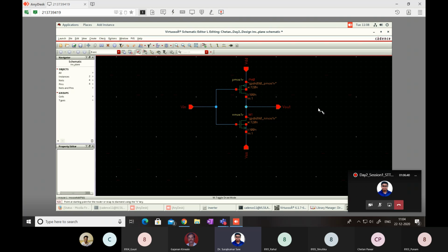Yes, you have given the value of A and B. Have you enabled them? I have to check it. Please wait. Stimuli. Okay, you have given. See, rise time and fall time you have to give, right? And pulse width also you have to give. Without rise time, fall time and pulse width, it will not run, I think. See, I have put some rise time, 10 nanoseconds. Again 10 nanoseconds for fall time. Pulse width you have to see.